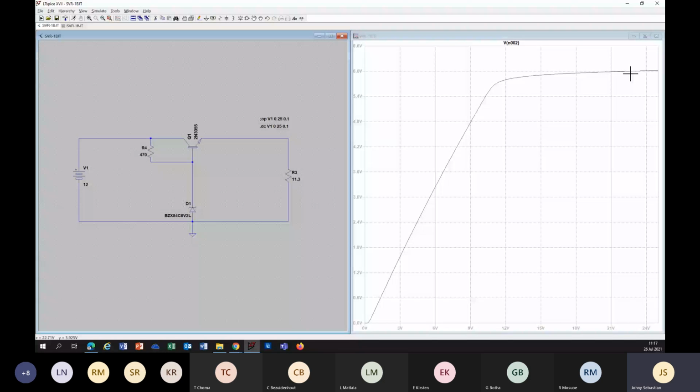So when the input voltage increments, output is somehow going more than 5.5. That is a possibility. Simple reason: your Zener diode, after a certain time, the power consumed in the Zener diode may exceed, and in that case our operation can be disrupted.